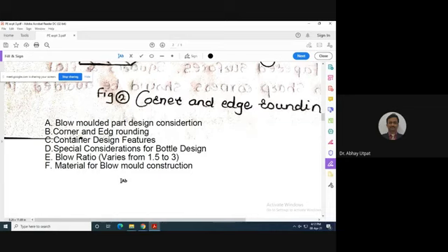For your kind information, we have also studied this in the third year subject metallurgy. Beryllium is a very costly material. That's why if we use copper beryllium alloy, the cost of the die will be far higher, and some economy must also be considered. That's why, depending upon the requirement, the material is selected.